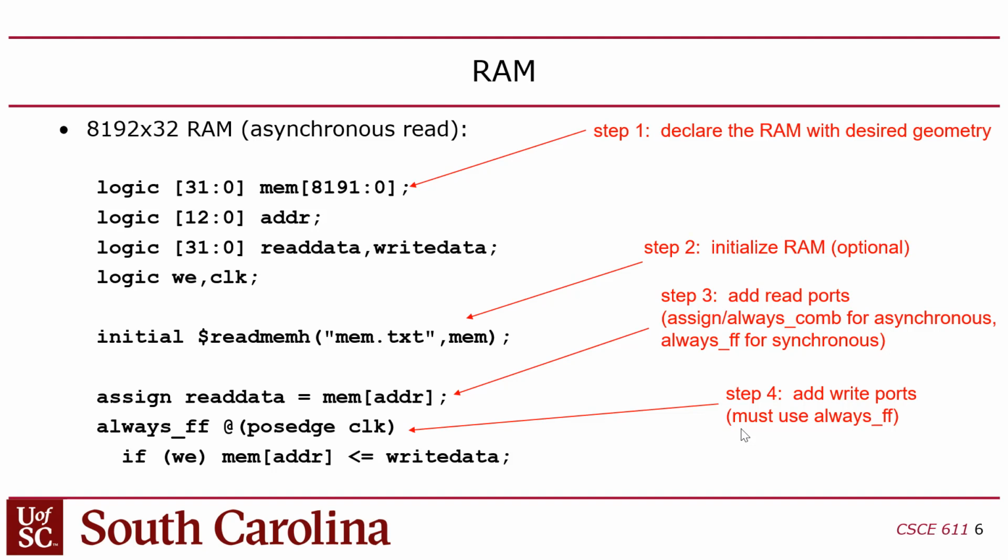The R-type instruction, essentially. The problem is that when you synthesize that on the FPGA, it actually ends up making a 2-dimensional array of registers with a mux for the output and a decoder for the writing part. You guys with me? Which is very inefficient because the FPGA has a relatively few number of registers. I think there's like 100,000 registers on the FPGA, but there's a lot more storage bits available on a RAM. But it won't actually target the RAM because the RAM has a synchronous read and it's limited to 2 ports.